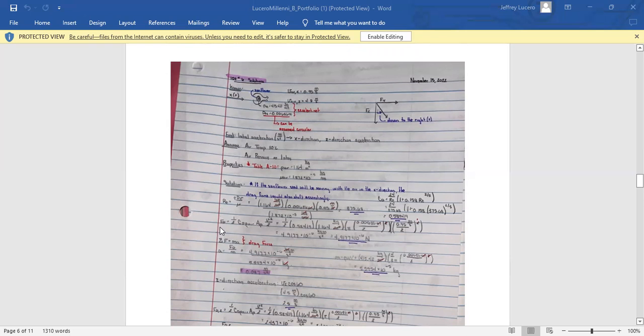0.589419. To get the drag force, it's 1/2 times CD times the density of air times the projected area times velocity squared. We can calculate the area projected from the seed, so it's pi times 0.00636 meters over 2, squared, times the velocity, to get 4.9177 times 10 to the negative 6 kilograms meter per second squared, which is a Newton.